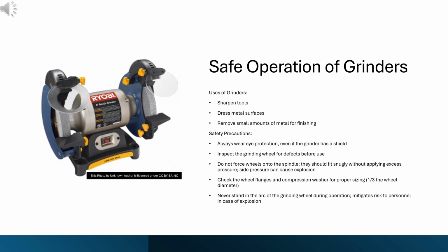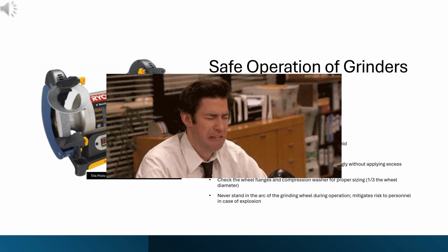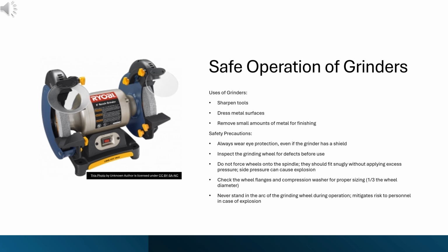Next up, grinders. No, not that kind. Calm down. Grinders are essential for tasks such as sharpening tools, dressing metal, and removing small amounts of material. For safe operation, always wear eye protection, even if a shield is present.